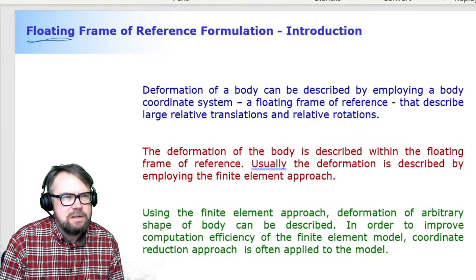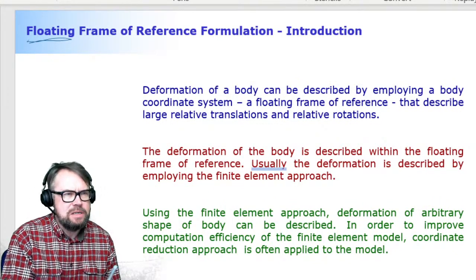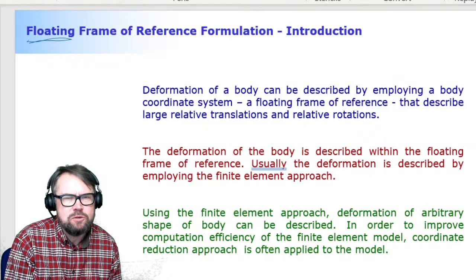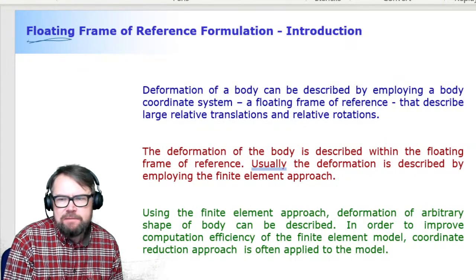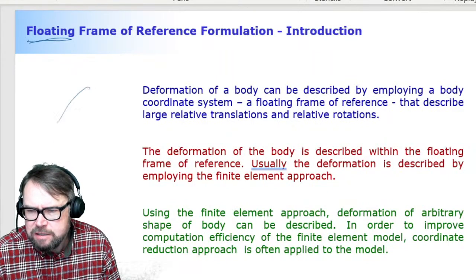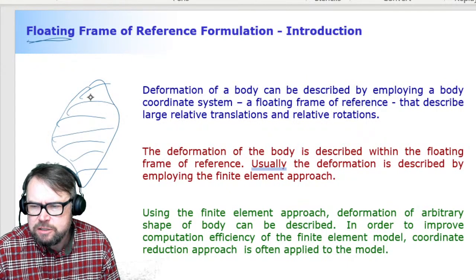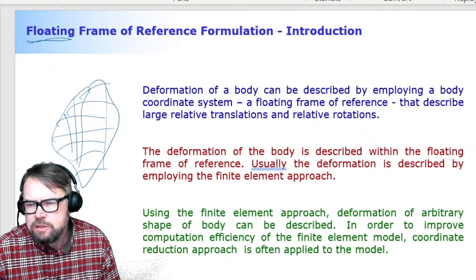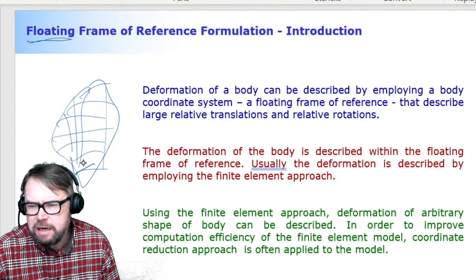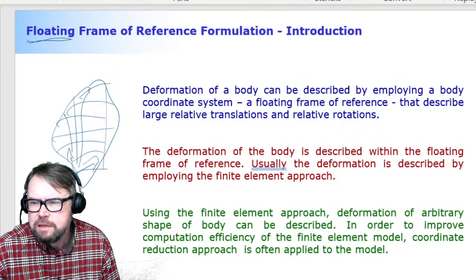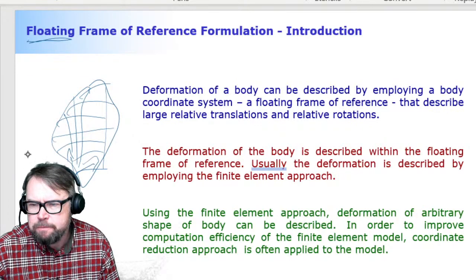Now, the deformation is described with respect to this reference coordinate system by using finite element modeling. Basically the idea is that you have this potato-shaped body. You model the potato-shaped body using finite element discretization. You can use plate elements like shown here. Once you're done with your plate elements, you're going to have your reference coordinate system somewhere. Let's place it here.